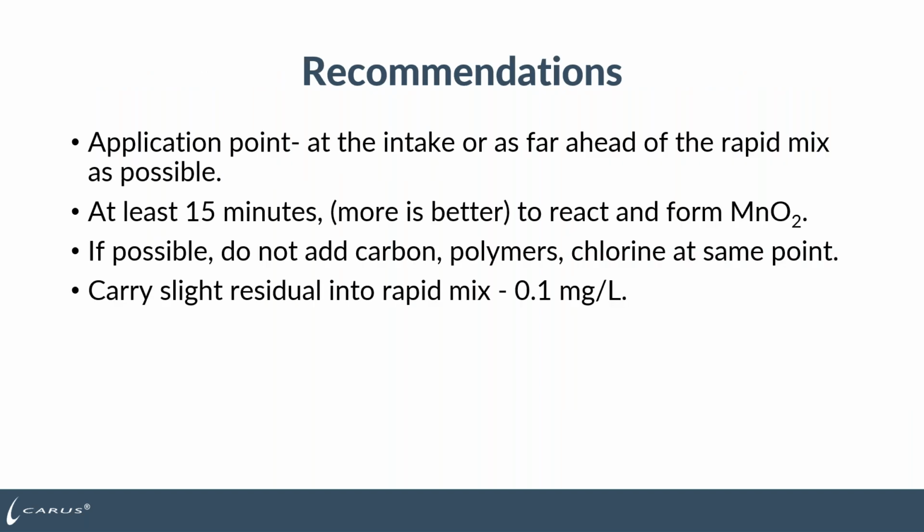So like I mentioned, application point will be the first thing that we'll discuss prior to a jar test. So are we going to feed at the intake? Are we going to feed at the rapid mix? What's the detention time we have? Ideally, we want about 15 minutes or more. If you've only got a contact time of 1 or 2 minutes, we're typically only going to really be reacting with the iron and manganese, so you're not going to get much benefit from reacting with organics.